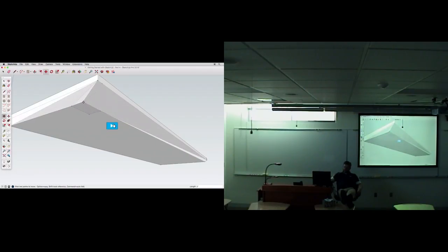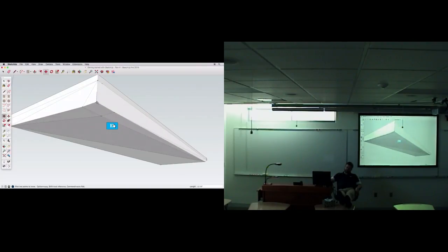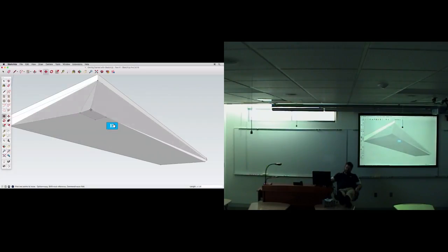That's what I was talking about, where you're moving one thing, but it's connected to other things, and so it changes the shape that you originally made. On top of the other edges, those edges merged. This is a key behavior to making SketchUp fast and easy, but it's not what we want in this example. This is one of the primary uses of groups, which will isolate our geometry, preventing the edges from merging.